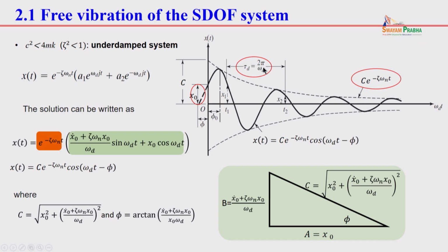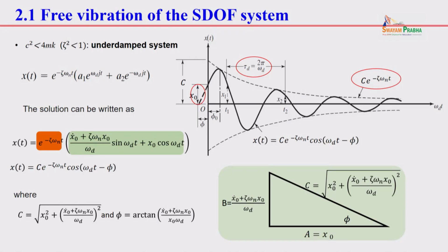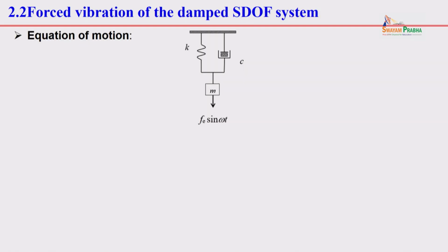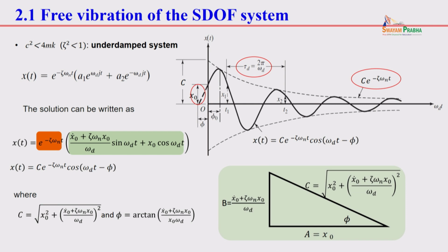So this figure is sometimes used for a wave tank test, where you give the initial position of the buoy, and that is the free decay. Then from the free decay, you can calculate damping, right? You can get the natural frequency. You can recover the stiffness. That is the experiment I believe Dr. Vijay will show you in the tank test. And later I will tell you this free decay is sometimes called the impulse response.